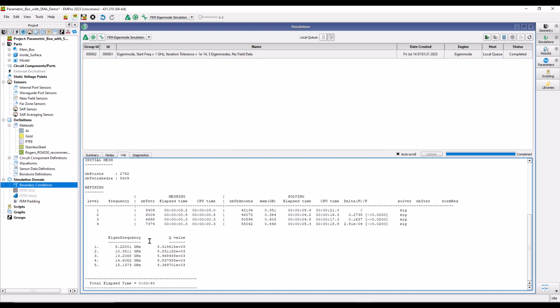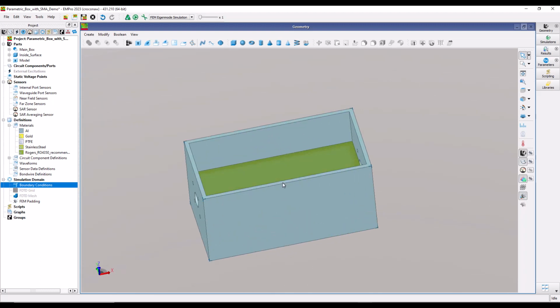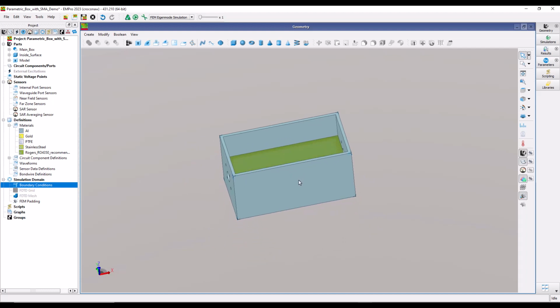Now, to get rid of this eigenfrequency, you basically have two choices. You can play with the metallic enclosure width, height, etc., which will force the natural resonance frequency to move up or move down so that you can clear up your desired frequency band. But most of the time you do not have a lot of leverage on mechanical size because your circuit is going to be part of some bigger ecosystem, and the cavity sizes have already been finalized or fixed due to the overall mechanical design of the system.